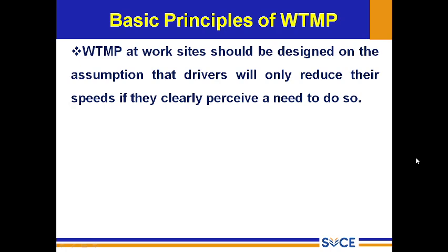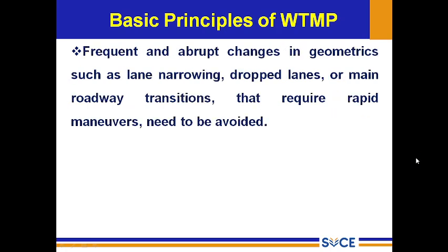So, whenever the vehicle is entering into a work zone, the driver should be able to understand whether it is necessary to reduce speed or whether with a normal speed you can proceed. So the signboards should be properly kept at appropriate distances so that the driver, if needed, can reduce the speed. That should be clearly placed. That will improve the overall safety of the work zone.